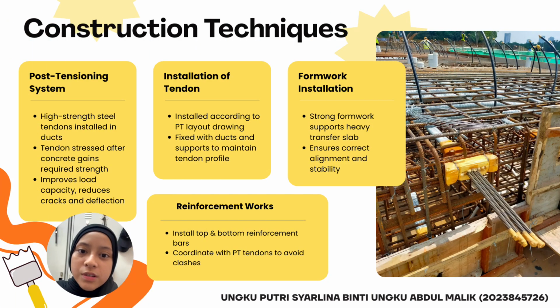Next, for the construction techniques, first, this project uses a post-tensioning system that I just explained in the previous slide. It uses the post-tensioning system because the transfer floor slab needs to support heavy loads. High-strength steel tendons are installed inside ducts and will be stressed after the concrete reaches the required strength. What are steel tendons and what is a duct? Steel tendons and ducts are equipment used in the post-tensioning system. We can see them later in the machinery and equipment section.